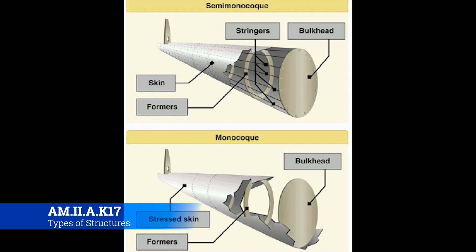There's still bulkheads, but there's one key addition, and that is longerons. Longerons run the length of the aircraft, and they usually extend across several frame members to help the skin support the primary loads. They typically are made of aluminum, and they're either a single piece or built-up construction, depending on where they're at on the airplane and the type of airplane.